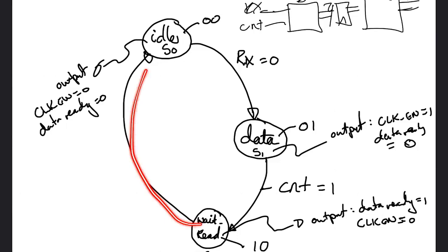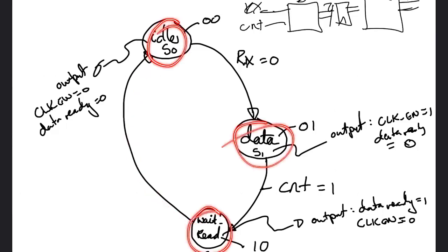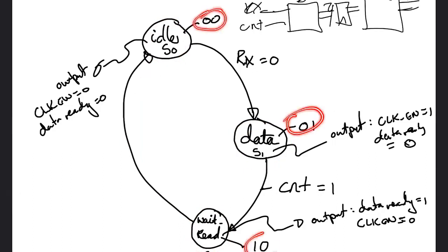So I've got 3 states: idle, receive, data ready high. I'm giving those states numbers, 00, 01, and 10. Because I have 3 states, I need at least 2 bits to represent them. I don't use the state 11. It's a not used state. Then I have to ask myself, okay, what is the thing that causes the transitions? Obviously, this is serial is low. So that's my one input into the state machine. RX is low, but in your case, you call it serial. So let me just fix this so there's no confusion. Serial and serial.